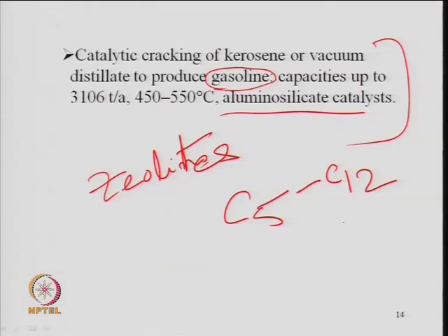So, one can control the octane number by controlling the product distribution, right. So, in general the gasoline is a hydrocarbon which has carbon numbers in the C5 to C12 range, right, and contains mainly paraffins, naphthenes, aromatics, but isoparaffins and aromatics are preferred because they have a high octane number. But aromatics also have certain limitations. Aromatics should not exceed 35%, and especially benzene is not desired, it should be less than 1% because of the environmental regulations, right.